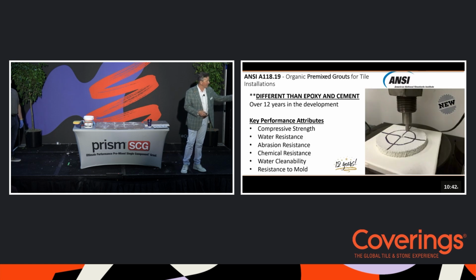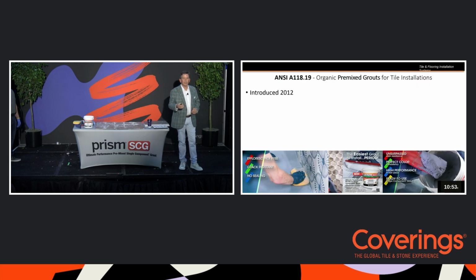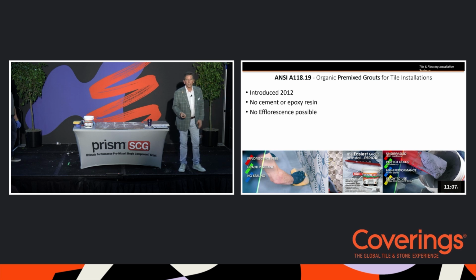So here we can see some of the differences between a premix grout and the epoxy and standard grout categories. The premix grout was introduced in 2012. That is 12 years ago. We've had premix grout now for 12 years. They have no cement. That's a good thing. They have no epoxy or harsh chemicals. That's a good thing. They cannot contribute to efflorescence. That is a good thing.